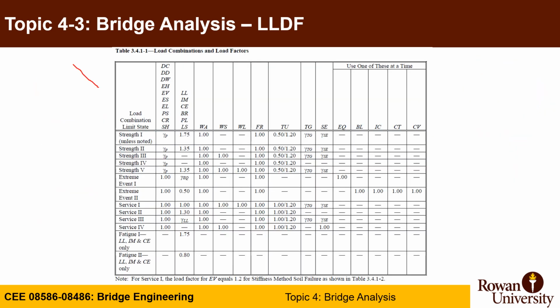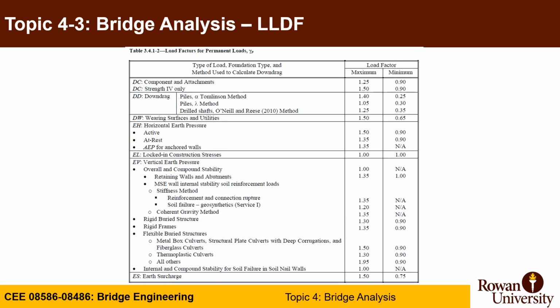We also are familiar with the load combination. We spent so much time defining the different load combinations and different load factors for dead load, live load, etc. We were able to get the loads from the unit weight of materials displayed in this table.